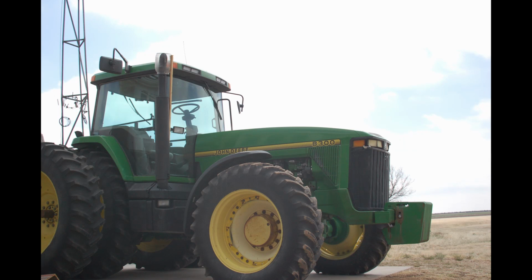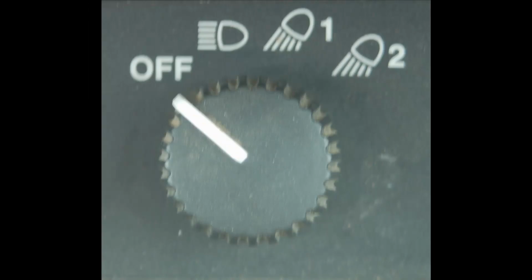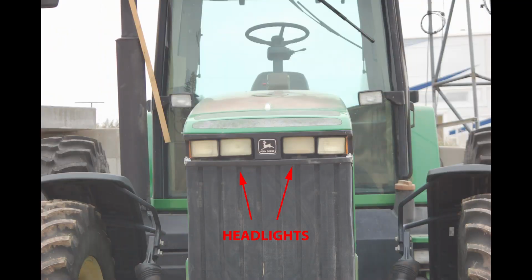On the 1995 John Deere 8300 mechanical front-wheel drive tractor, the headlights are controlled by a 4-position, multi-function rotary switch on the side panel and the dimmer switch on the steering column. The lights designated as headlights are the 2 inner lights on the front of the hood above the radiator. They are dual-function high and low beam lights. The outer 2 lights are called the front floods and will be addressed separately.